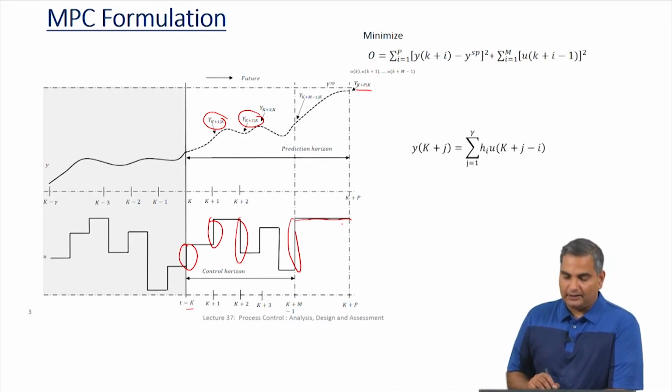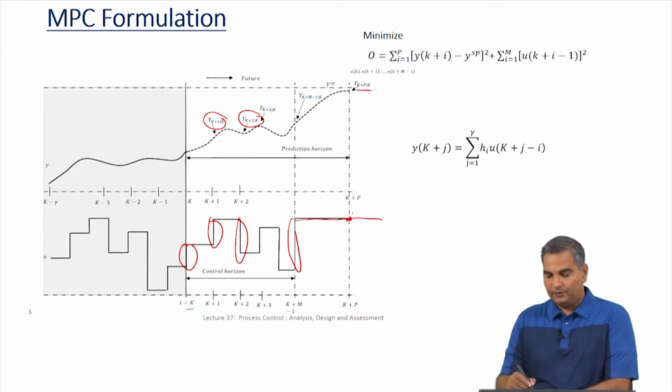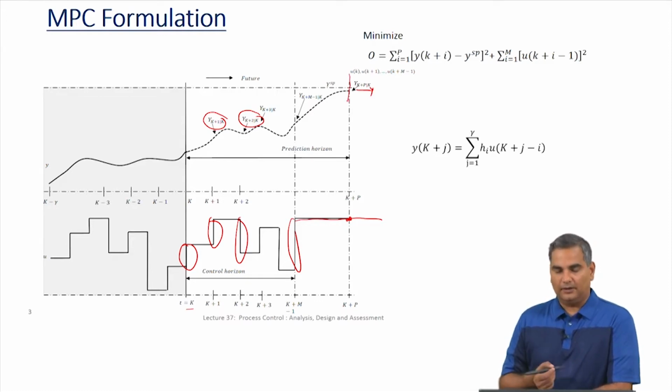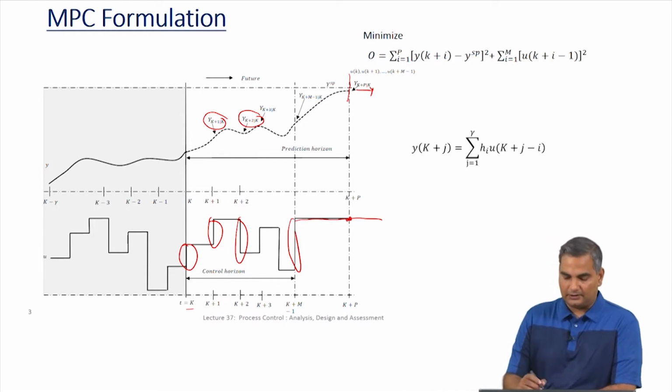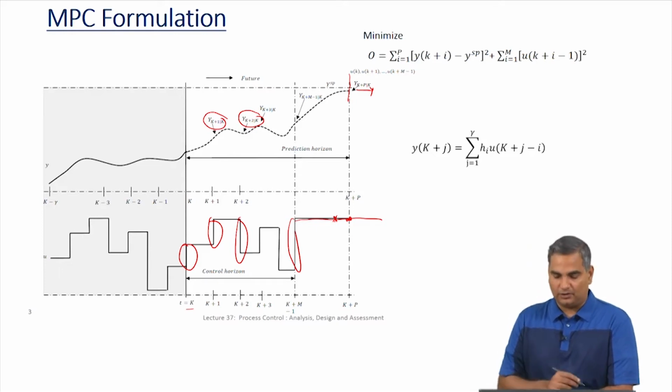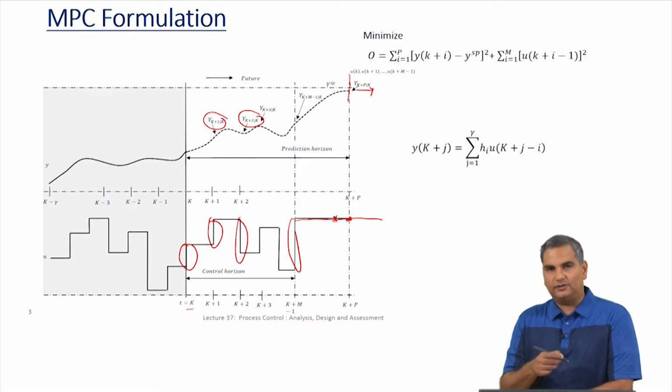And we also said that it does not really make sense to go beyond the prediction horizon, because a change that I make here will only affect an output after this, but our prediction horizon itself stops here. And if you assume the systems are causal, strictly causal, then up to k+p-1 you could have kept making these choices, but we use this as a tuning parameter.